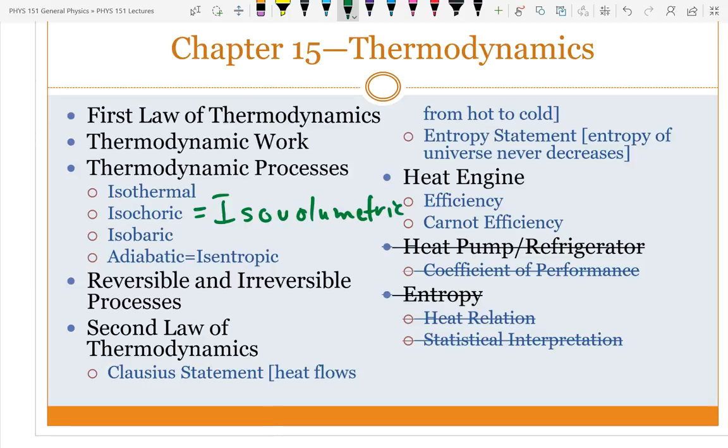I gave you a homework problem that asked you to relate the change in internal energy, the work, and the heat for all of these. I was going through it with a few students this morning, so you can see the first parts A and B done if you go to the right place on OneNote. You have to be aware that it says specifically it's talking about the work done on the system. In class, we've always talked about the work done by the system. If the system is doing work, work done by the system is positive, then energy is going out. If work is done on the system, energy is coming in. So you have to pay attention to those little words.